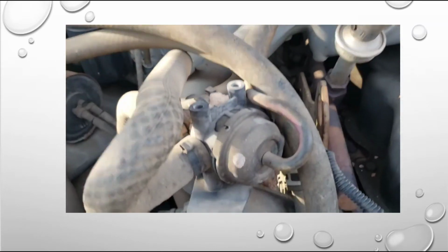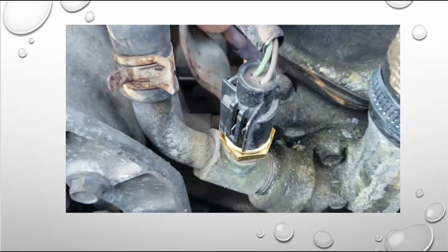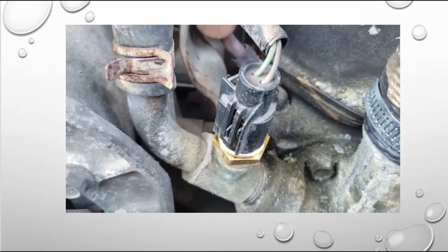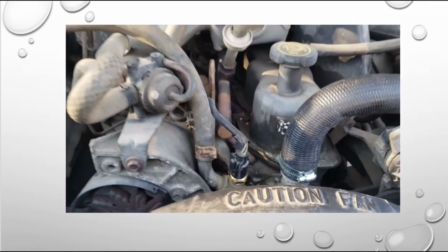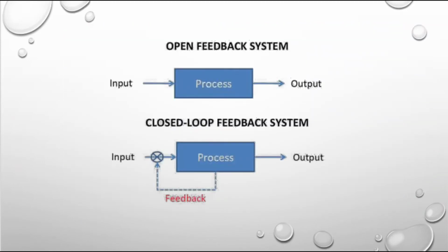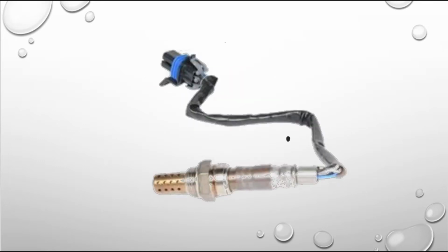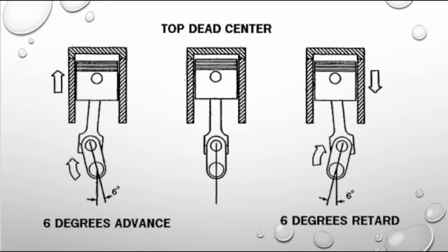Coolant temperature sensor. The engine coolant temperature sensor is very important because its input is used to regulate many engine functions. It can activate or deactivate the early fuel evaporative system. It controls the open and closed-loop feedback modes. During open-loop mode, the coolant temperature sensor controls air-fuel mixture until the engine warms up and goes into closed-loop mode, where the oxygen sensors will take over. It controls the startup fuel enrichment on fuel-injected engines. It controls the spark advance, or spark retard.